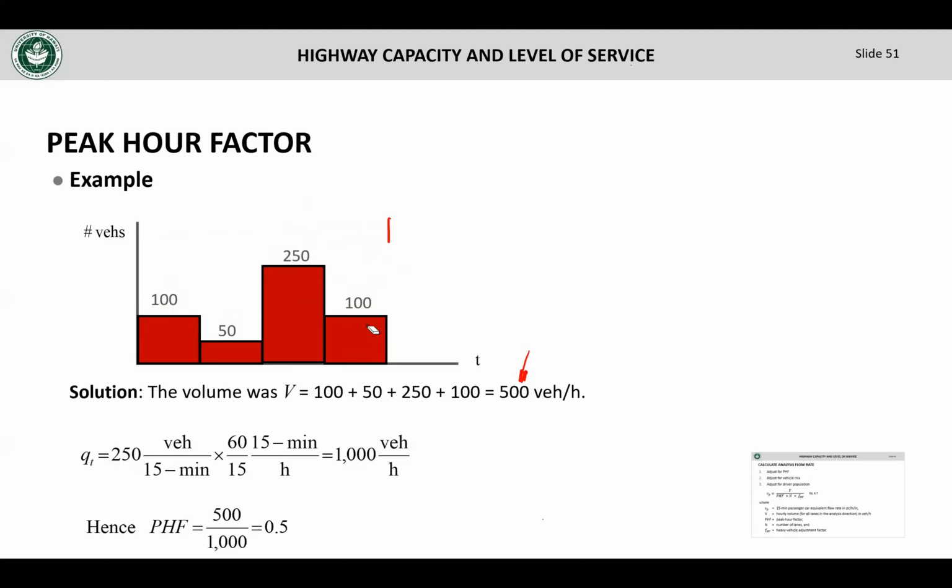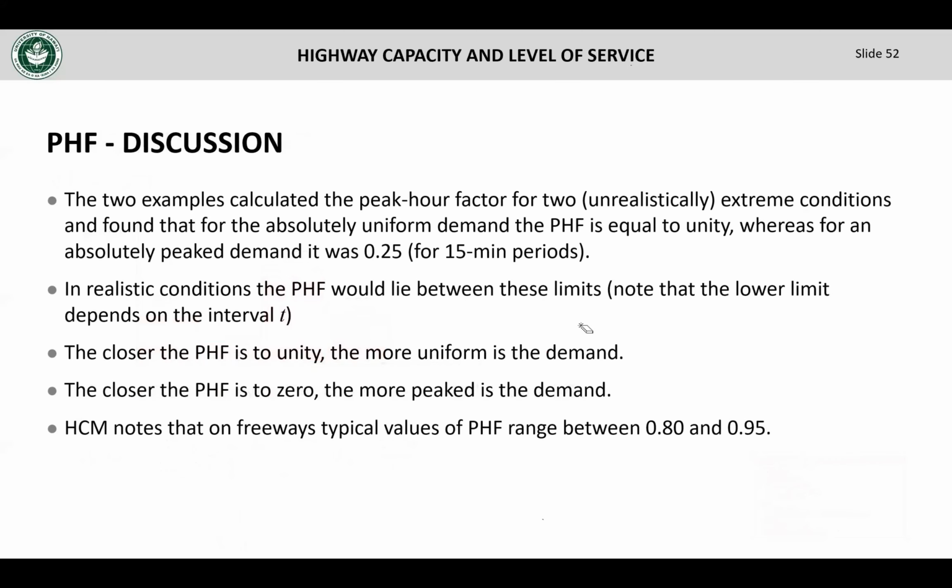Okay. So we are making analysis. In reality, what we're going to be doing is making analysis with vehicles per hour, but we're analyzing the most critical 15-minute period. That's what basically we're doing with this analysis. And that's why we increase that volume to account for that.